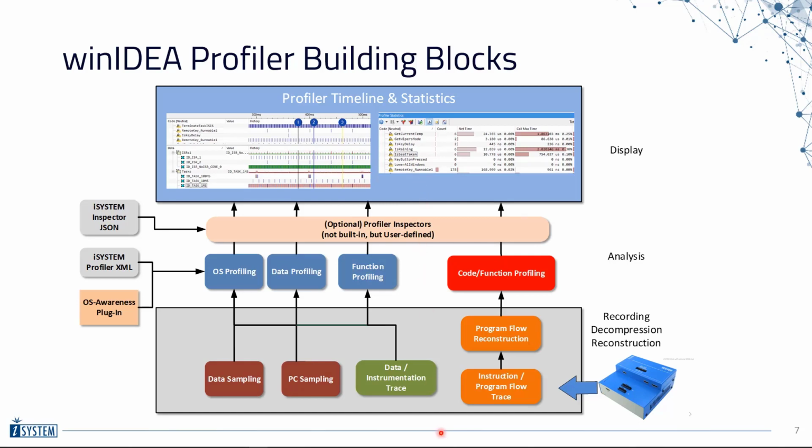The other type of trace information is based on data trace, meaning the trace hardware in the chip captures the data written to specific locations and sends this data out to the tool, along again with some timing information. By knowing how to interpret the data written to the specific locations, the profiler can derive various types of information from this. The data written could, for instance, be used to mark the entry and exits of specific functions. So this is used for function profiling.